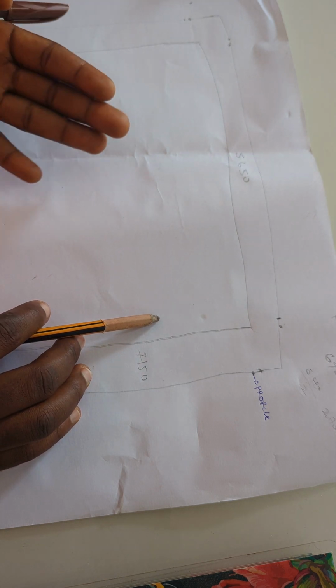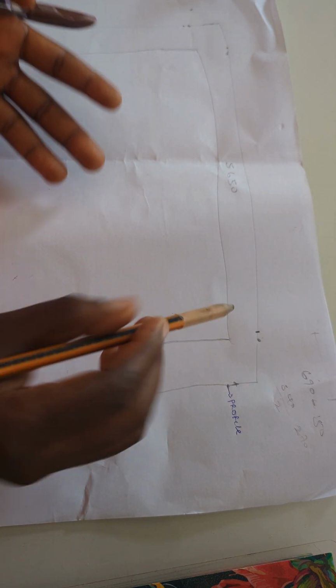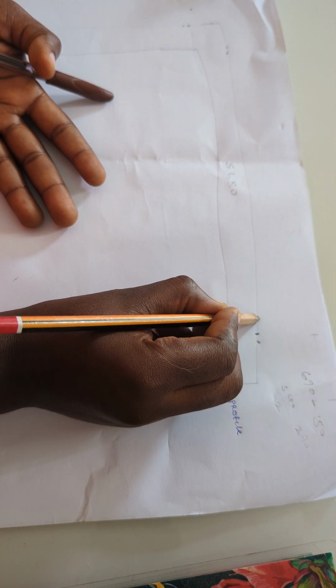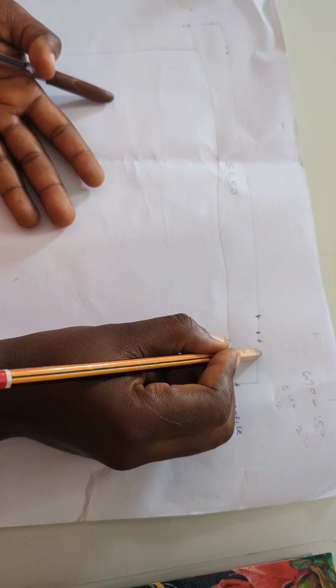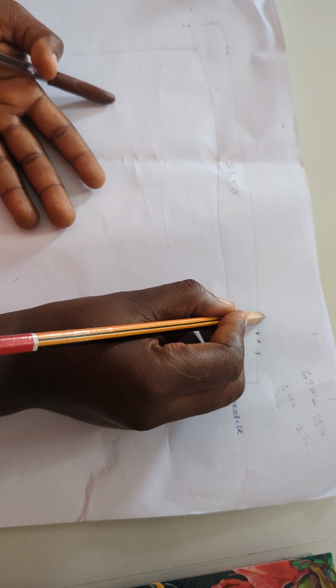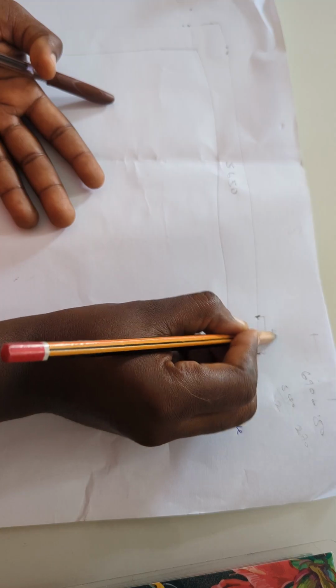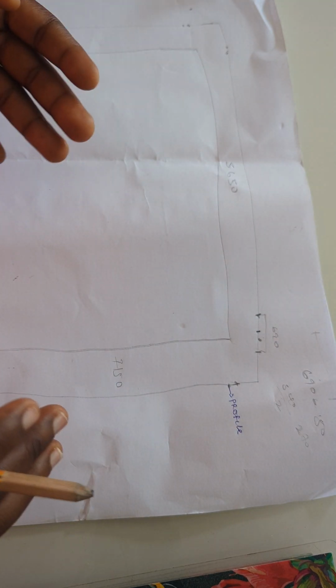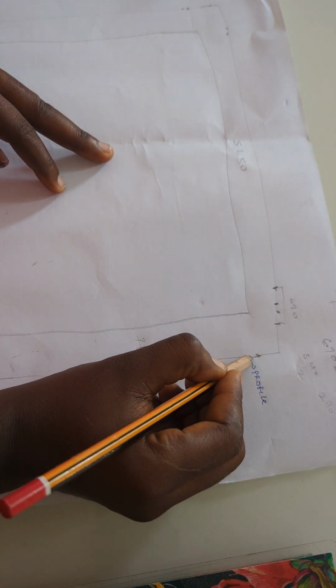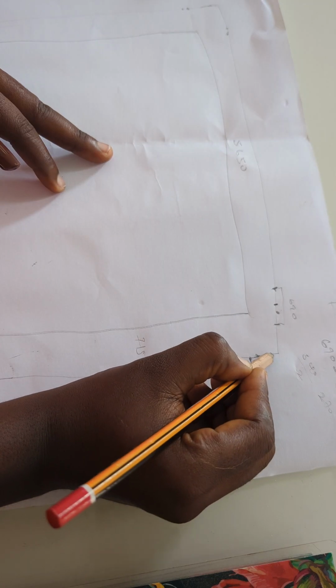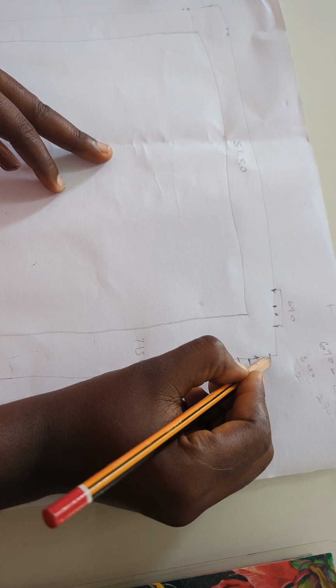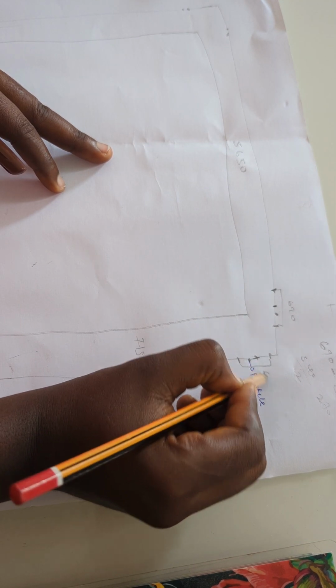Is that clear? If it's not clear, don't worry, it will be clear. So what I mean is from here to here, take your 270. From here to here, take your 270. So this entire width like this is 690, and that is what we are going to excavate. We are going to do it for here too. Here, come in by 270, go out by another 270. It means from here to here is 690.